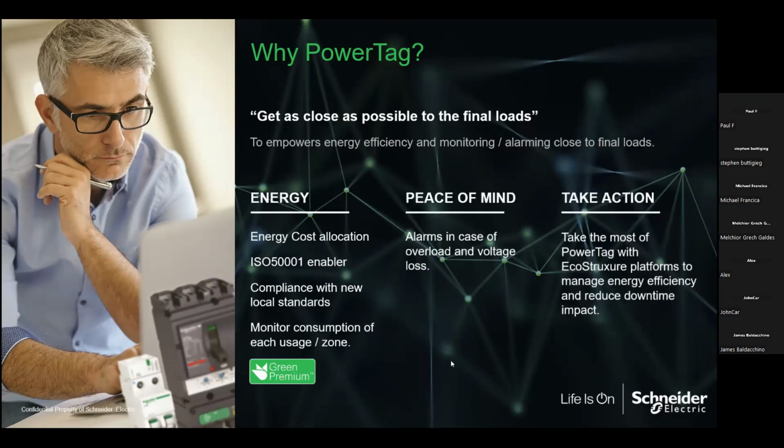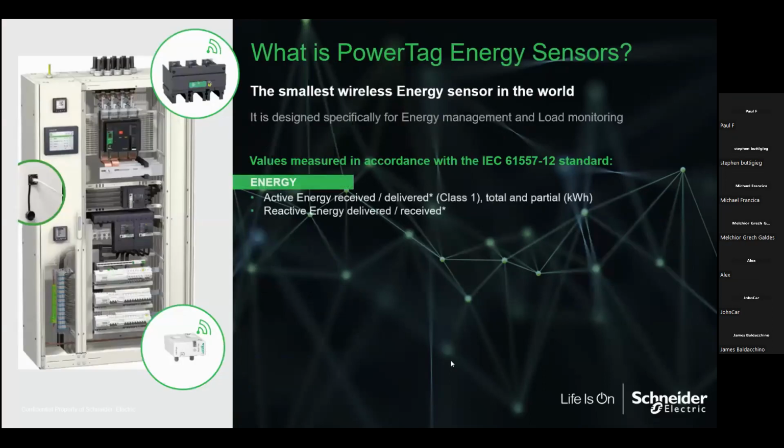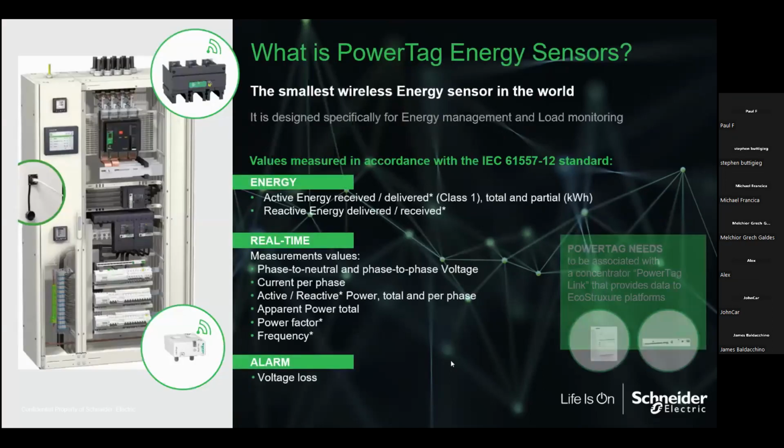Okay, so here are the measurements, or here is the power tag. It measures phase-to-neutral and phase-to-phase voltage, current per phase, active and reactive power total and per phase, apparent power total, power factor, and frequency.